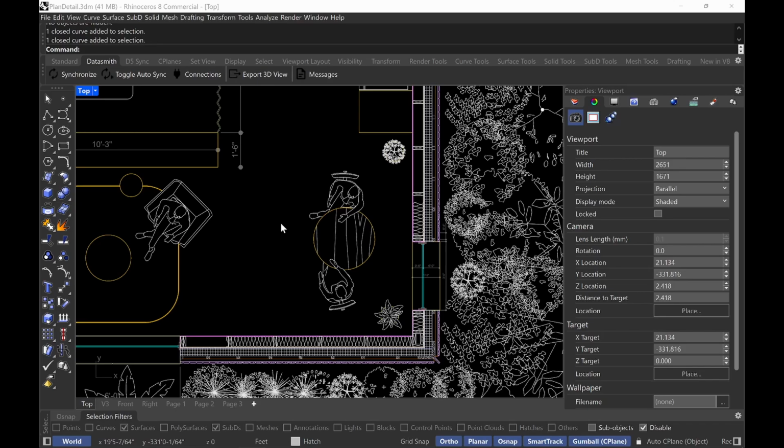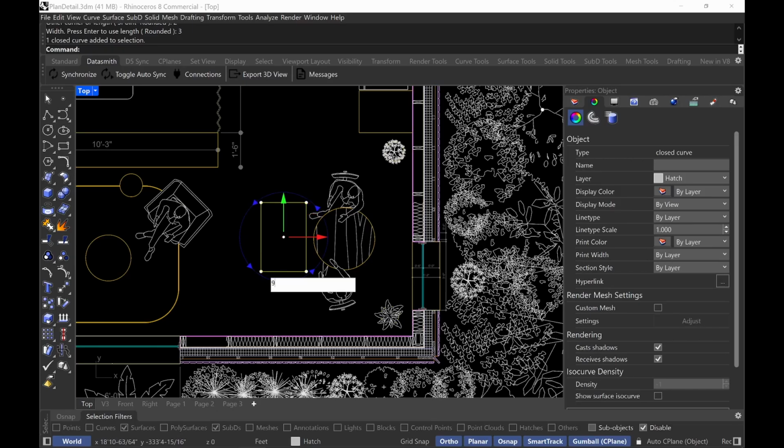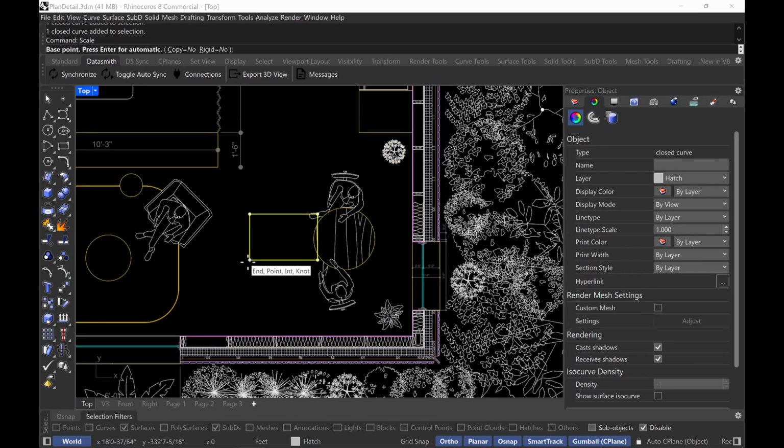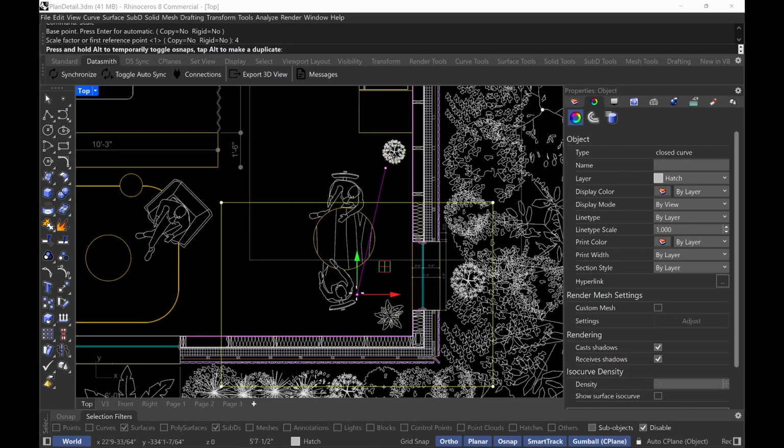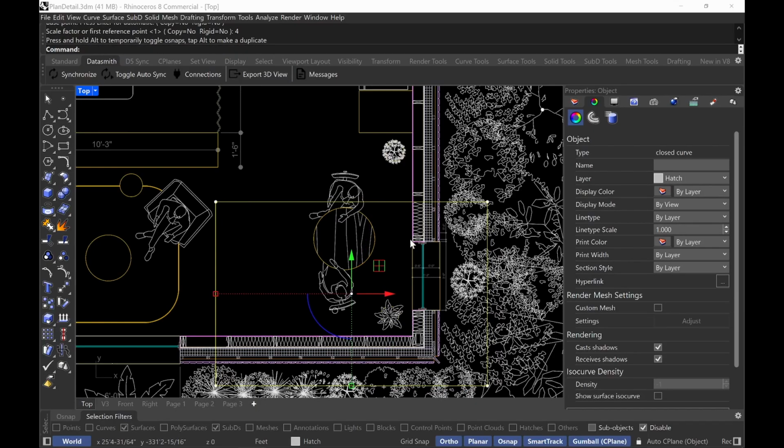We don't need to export the entire drawing. We just want this bottom right drawing. So we're going to do a rectangle with the center option, 2 feet by 3 feet, 24 by 36. Let me rotate it 90, and then scale it by the scale factor. Again, if it's 3-inch, it'll be a scale factor of 4. And let me move it something like this.